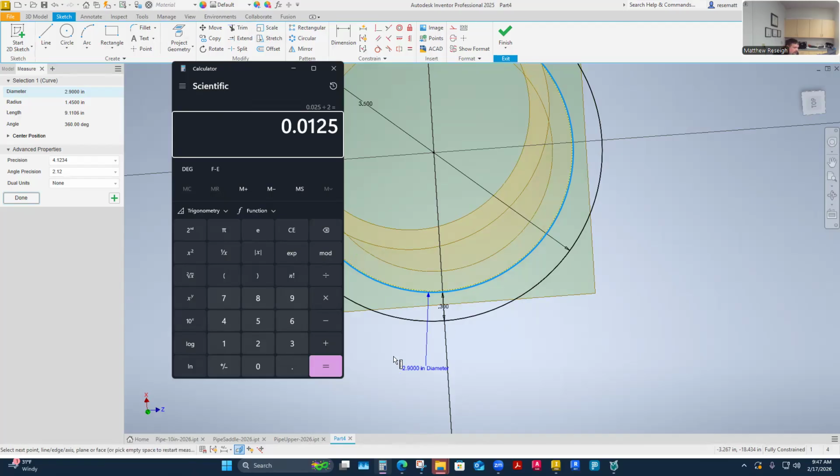And so this is a good conversation to have with an engineer. Should I use schedule 80 for this one or schedule 40 with a big gap? And they might be like, oh, let's just use schedule 40, because we know there's going to be a little grinding potentially anyway. An 1/8-inch gap, it's pretty easy for them to fill.